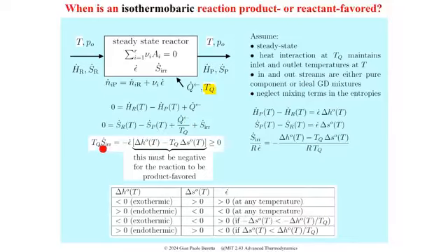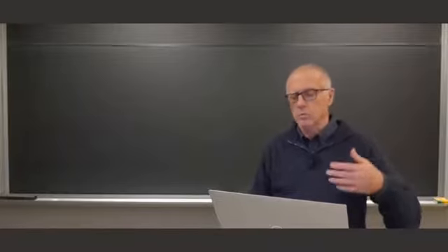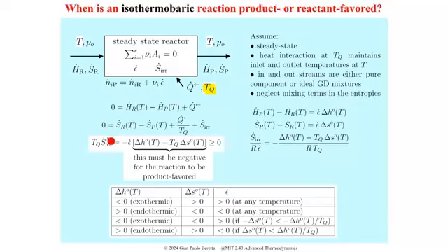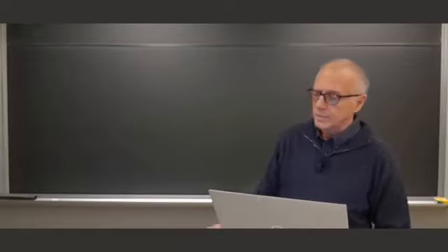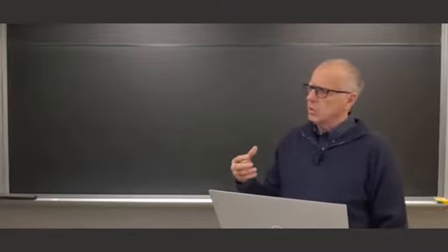And here's the outcome. It gives the entropy production by irreversibility multiplied by TQ, the temperature of the heat source, or say heat bath or heat reservoir, thermal reservoir, whatever you want to call it, is equal to minus epsilon dot, which is the reaction rate, the rate of the reaction coordinate, times this combination of the enthalpy and the entropy of reaction, which looks like the same kind of combination that we have in available energy, or actually exergy.